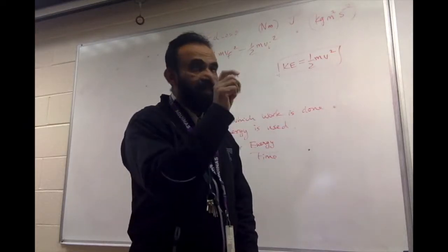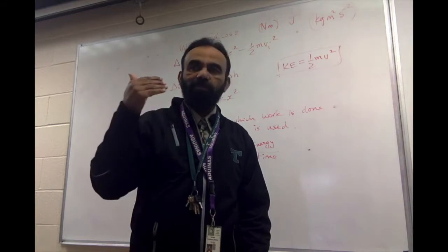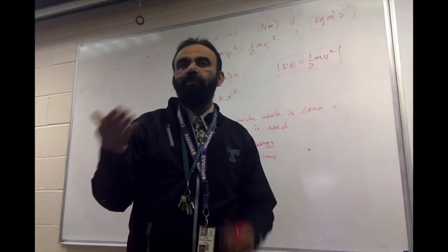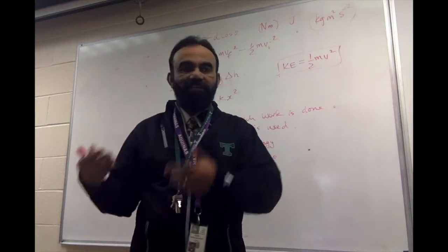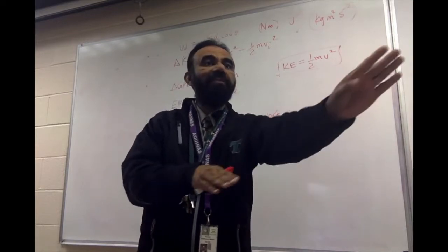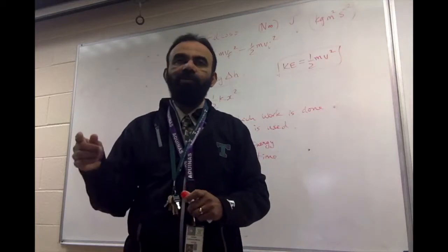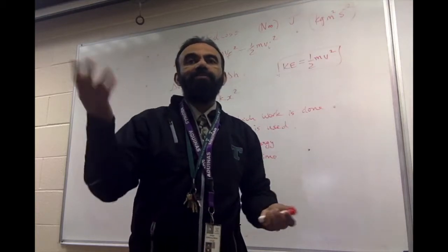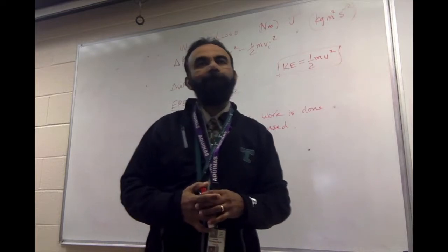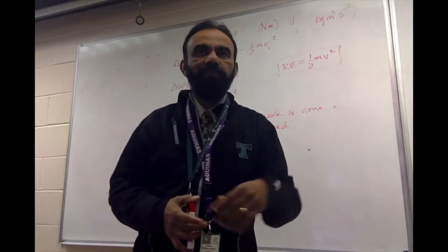But these days, the dimmers that we have are all solid state. Solid state means more electronic type. So what they do instead is it takes 110 volts and then it reduces the voltage itself and then sends just a little voltage for it to operate. So it controls it in the form of voltage, and so you're saving power. So what does it do with the rest of the voltage? You can actually drop off the voltages by different methods.